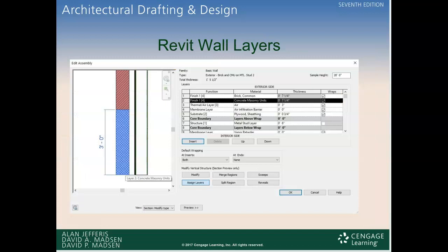Revit walls are also like that. They also have their own set of layers. So you can start with the outside exterior and move your way in, and that same thing is shown on this Excel spreadsheet, indicating the little pieces that go up to comprise a wall. It can show you what the total thickness of that wall is and also how high, and you can change any of these variables.